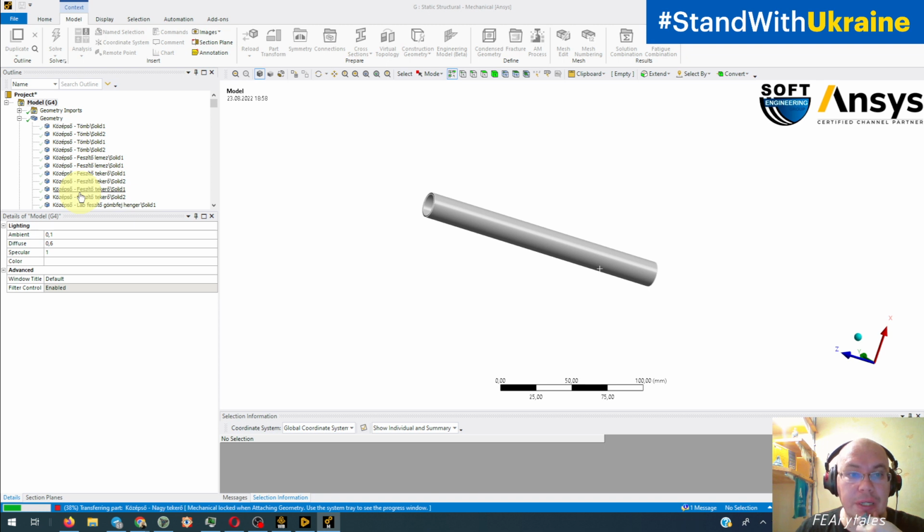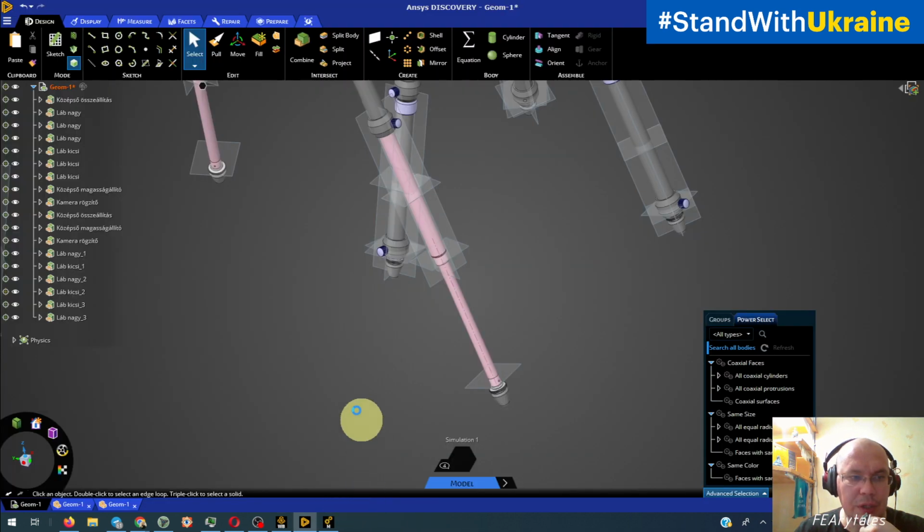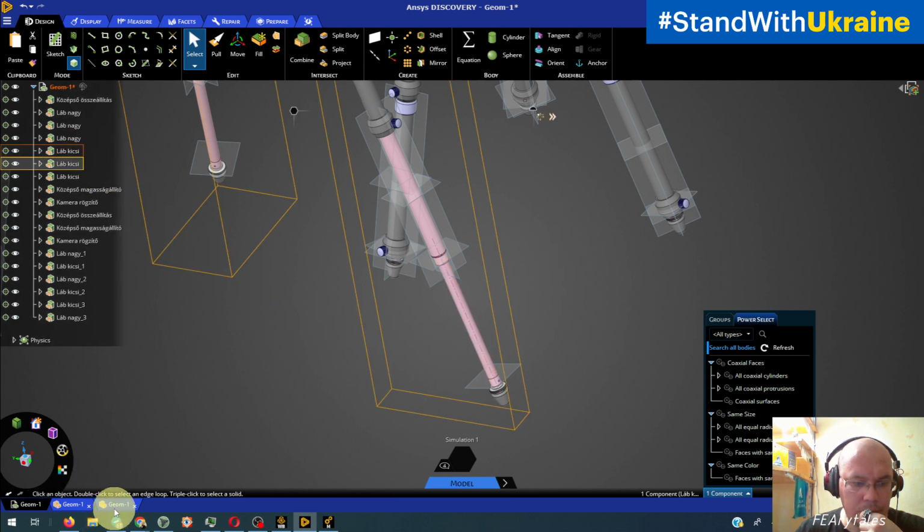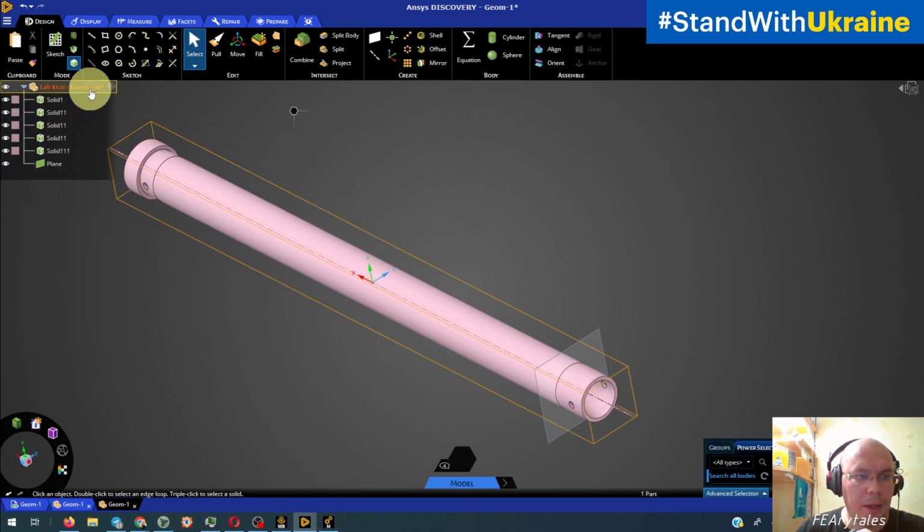And we have a much better mesh for those objects, but it will be an inconsistent mesh. If we want to create a consistent mesh, we need to do some additional changes with this object. We need to find this object or open it here and say that we must have shared topology.